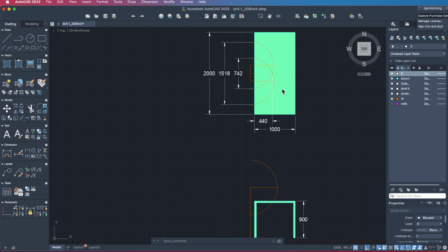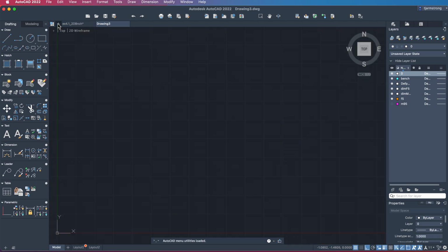Now, one of the last things we did was to actually create an external file with the stick figure for the 5 percentile female stature and the bench that we will subsequently import into our shop view. Okay, so I'm going to create a new layer here for making our shop. And if you look at the directions for the shop, you'll see that the dimensions are given in meters. So I'm going to set my dimensions for meters for this one.